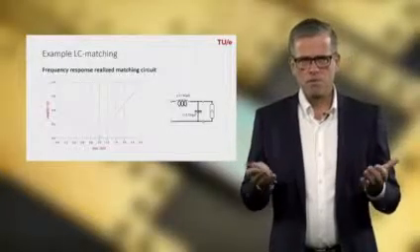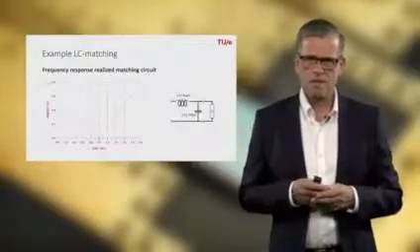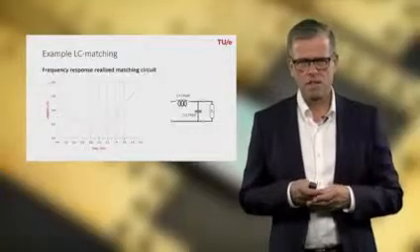If you want to improve the bandwidth of such a matching circuit, if you want to make it more broadband, then you could add more components to create a more complex matching circuit.